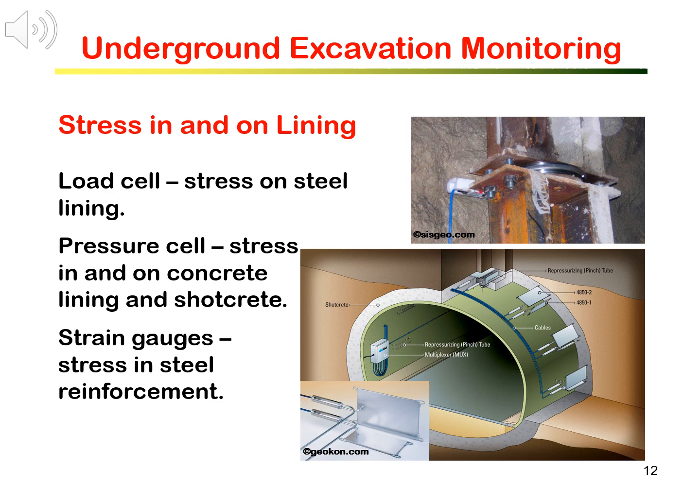In addition to monitoring the ground, supports are also often monitored to check the loading and the stress condition. Support monitoring includes measuring stresses on the lining and in rock bolts by different stress and strain sensors.